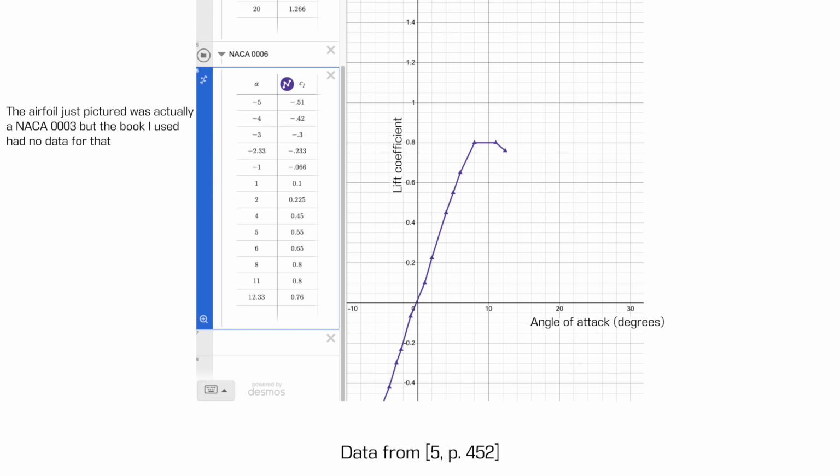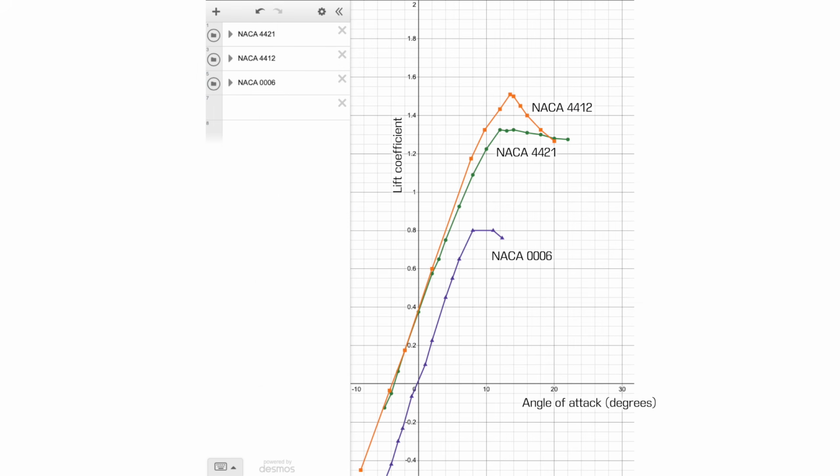This process results in a smooth stall similar to that of the trailing edge stall, however, the maximum lift coefficient of a thin airfoil stall is much lower. Because of this, very thin airfoils are not very useful at low speed flight, but they are useful for supersonic and low hypersonic flight for reasons that will be discussed in the next wing tutorial video.